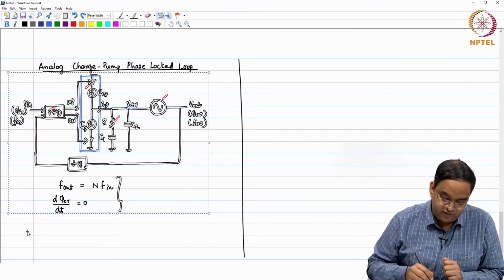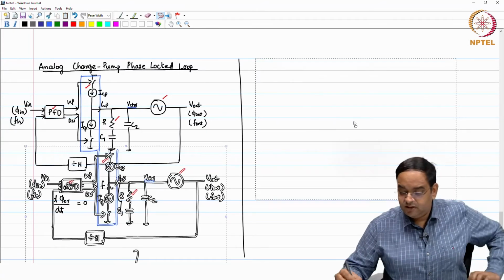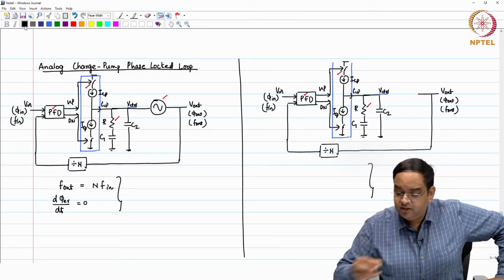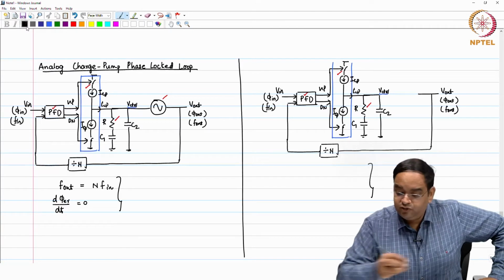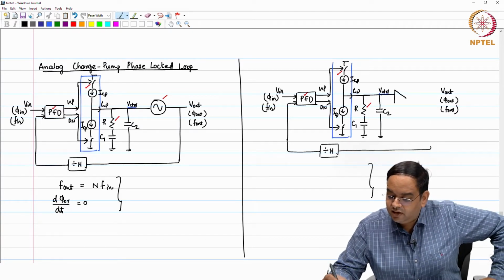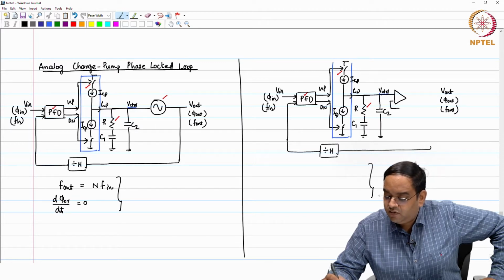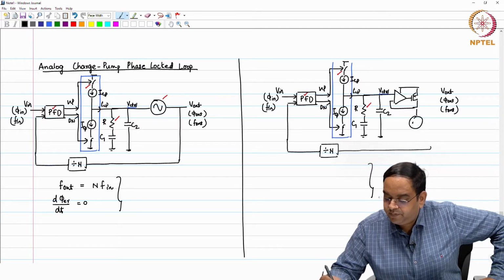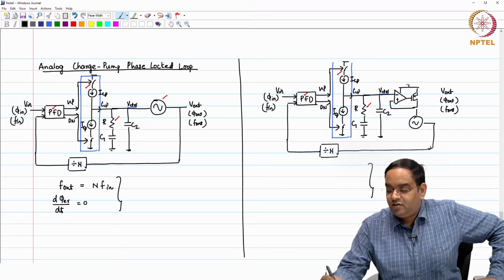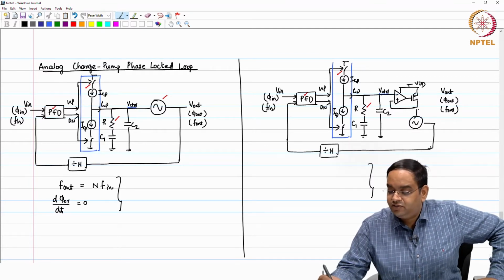This oscillator was not directly controlled in this manner, it was controlled using a voltage regulated design. So, we had a voltage regulated loop which controls the current through the oscillator. Okay, and this is VDD, VCO in our case.